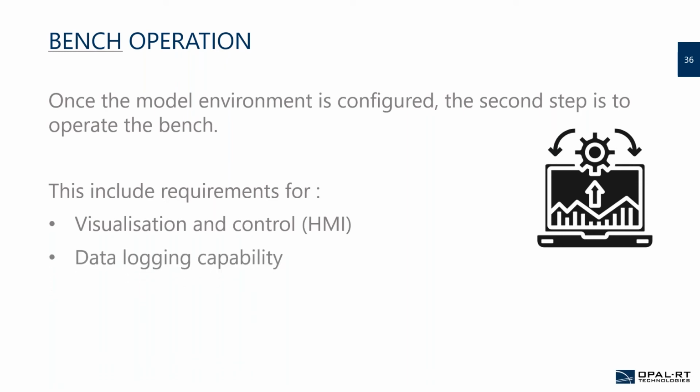You want data logging. When you test an ECU, basically the goal is to figure out something that doesn't work accordingly. So you want to be able to log this data, to record it, to see what's going on and make the correct corrections to your systems. Then for sure, when you have a nice flow, you want test automation, especially scripting. You want the bench to operate by itself, run a bunch of tests, and have a pass or fail report at the end of the day.